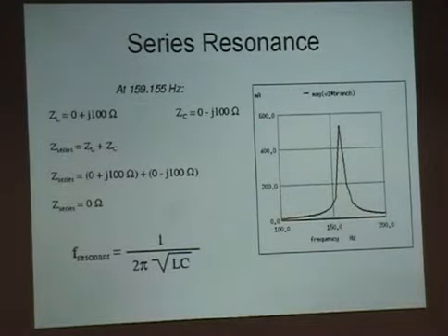Applications of resonance. Well, I've gone through them, but a tuner, you can choose your frequency. You can choose the frequency from the whole radio spectrum. Your radio normally is either an HF or a medium frequency, low frequency, or a VHF or a UHF, so that kind of limits what's actually going to get in. But the front end of a radio almost always looks the same. You're going to see some form of tank coil, tank circuit in there with a tunable capacitor or even a tunable inductor.